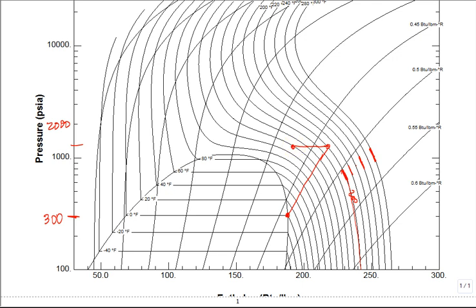Okay, now what do I do with this one? I want to put it through the expansion valve and do isenthalpic expansion, which is a straight line down. I got myself a problem. I didn't get way over here where I have a high quality where I can get a lot of evaporative cooling with this CO2, did I?